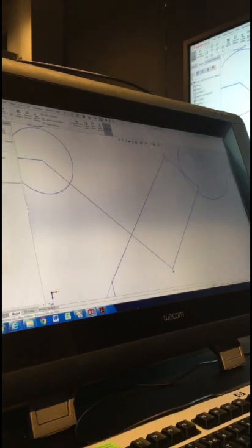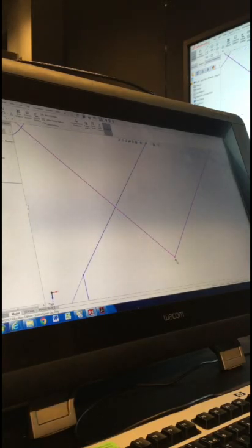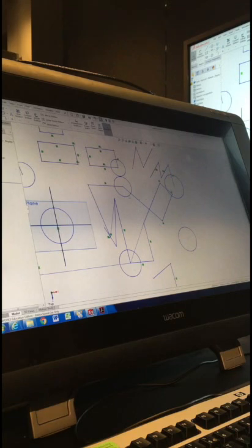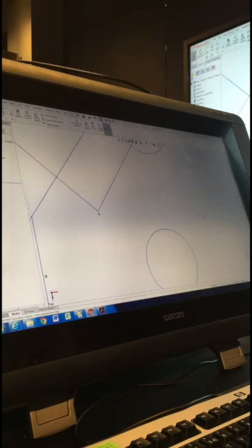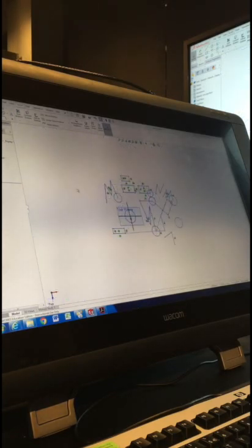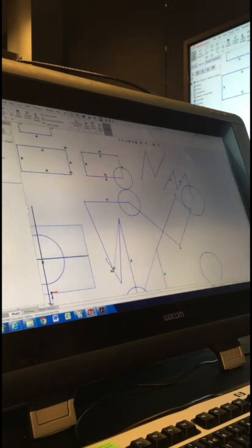Over here, we have some lines that are on some angles. This is a perpendicular relation, which means that those two lines are at a 90-degree angle. Okay. Now, there's a lot of different relations out there. We haven't touched on them all yet. A couple others we'll look at when we get into the first project parts. But they are very important for setting up our sketches.